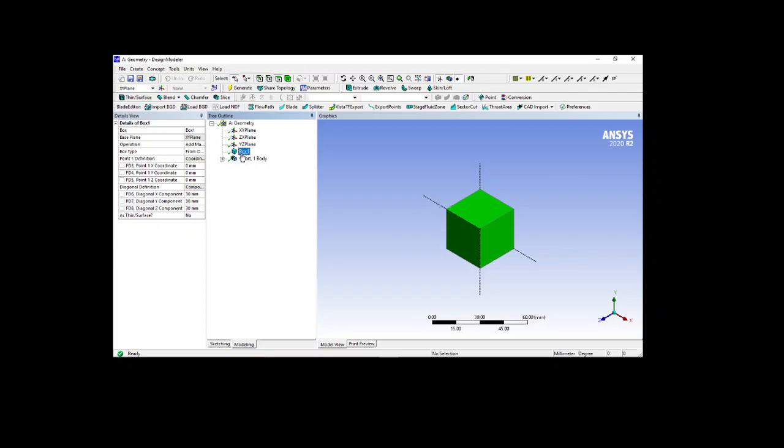Either you select the parts like this, and also by clicking on geometry. Here is the point selection, and it will help to select points. I will left click it, go back into the geometry and try to click the edges and corners. It will give some points. So you can click, and you may see a green color here, that is a point of the geometry.